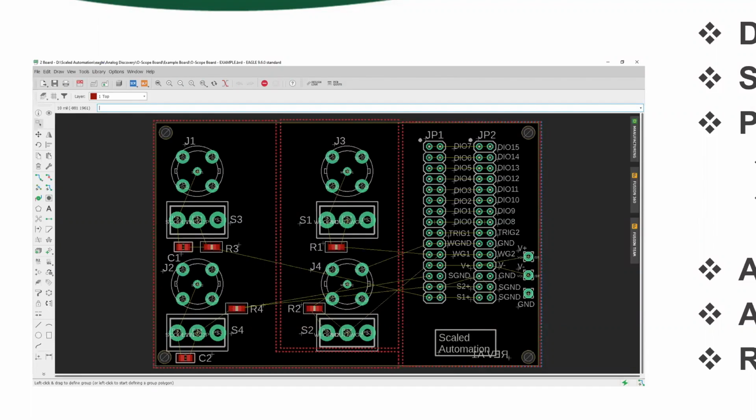Hopefully that's visible on your screen. Those little yellow lines are not traces yet, and you can see that they cross over. When you're placing components, you can look at those little yellow lines and figure out where to place components if there are options, and minimize the amount of crossover of traces. That'll make it a whole lot easier later when you turn those into traces.